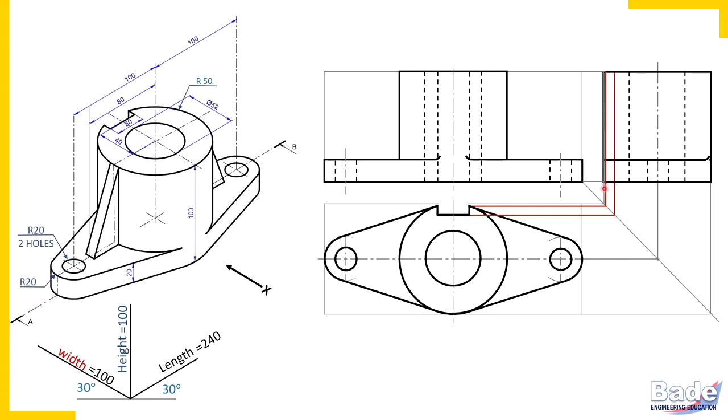Now, as I told you, the boundary generator is no more there, that is to be erased. So I have erased it. And this rectangular slot, watch here, this is a rectangular slot here. You never draw a hidden line at the boundary, remember. So this is a boundary edge of the slot, and these are the hidden edges of the slot. So this is how we have completed the slot in all the three views.